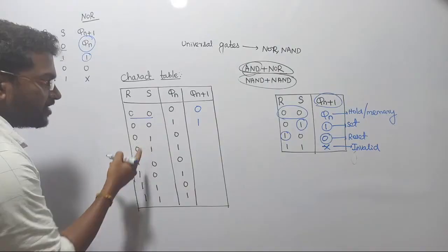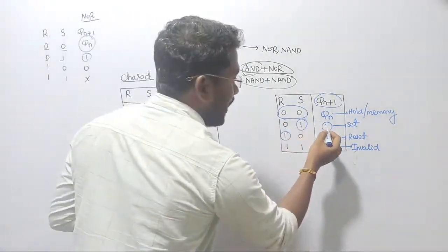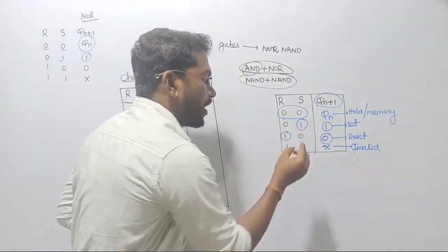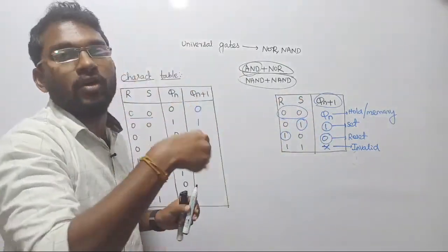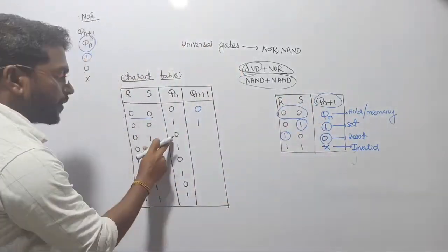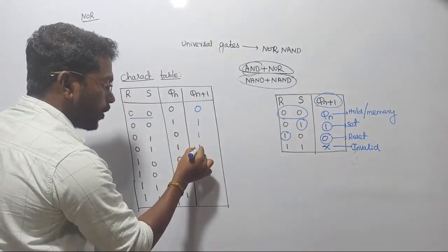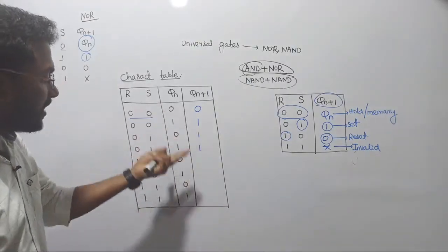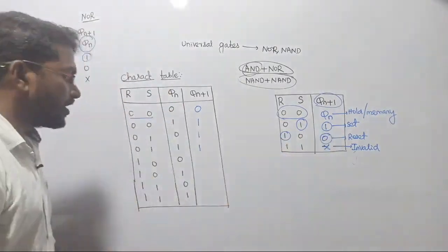Next one, while passing 0 1 as the input for your SR flip-flop, it clearly indicates its present output is going to be 1. It means while passing 0 1 as the input, the present output of the system, irrespective of the past responses, simply sets its value as 1. Whenever we are passing 0 1 as the input, output is permanently fixed as 1. See that 0 1, 0 1, in both cases output is going to be 1 1. In this case it won't care about the past values because it is permanently fixing its value. So that is the beauty of your system.